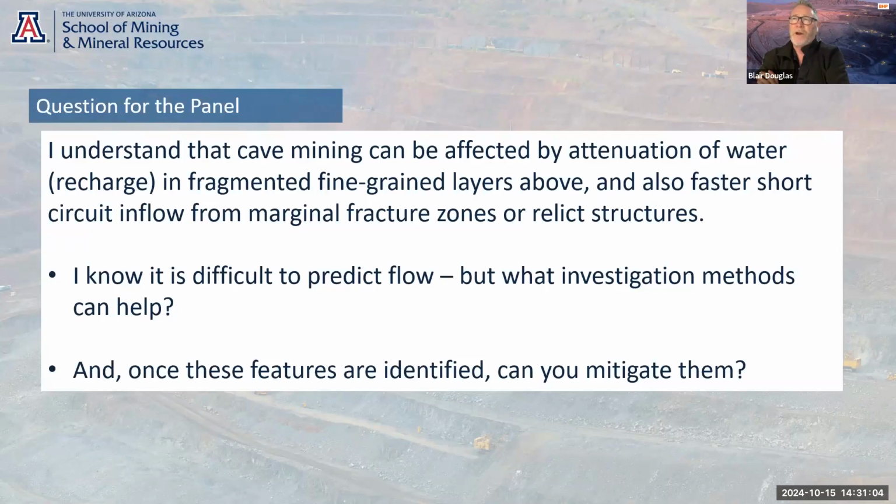And obviously the vibrating wires drilling becomes extremely important, but so does the structural model. Nothing can be done in isolation. I know we talk a lot about what we do as hydrogeologists, but really integrating hydrogeology into the geotech models and the structural models becomes imperative for caves, and using those structural models and developing them out to really know where you need to land vibrating wires, where you need to land instruments. It can't be guessed. It's got to be using some knowledge base, and that knowledge base is typically associated with the structural developments.